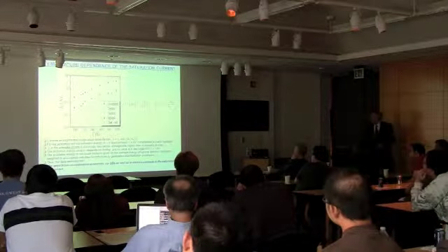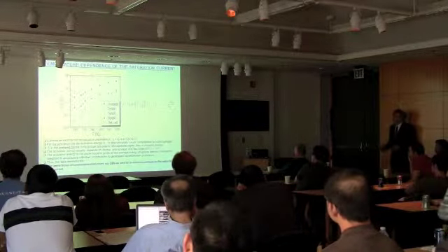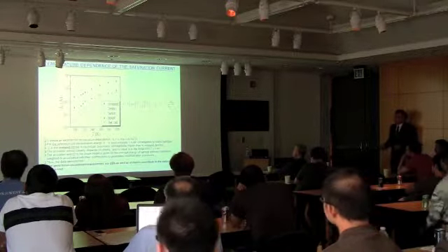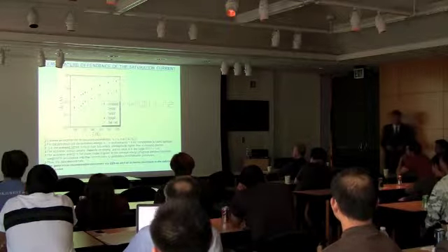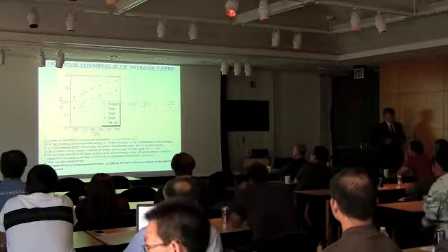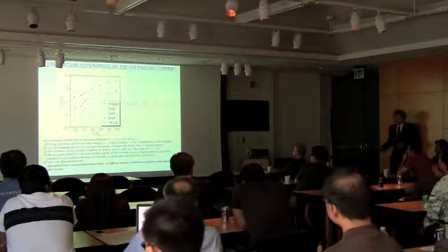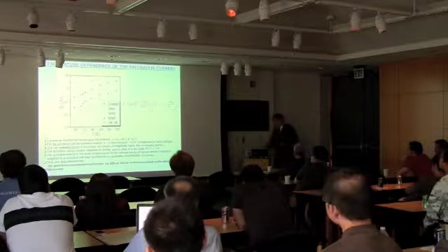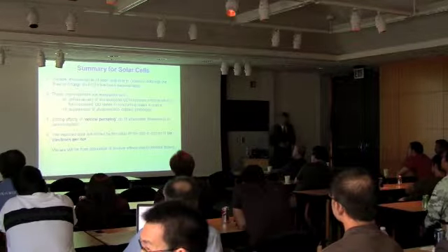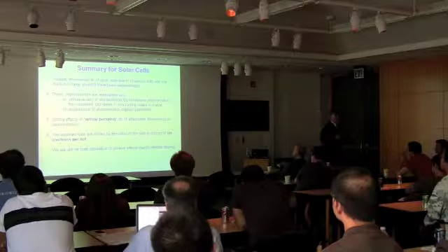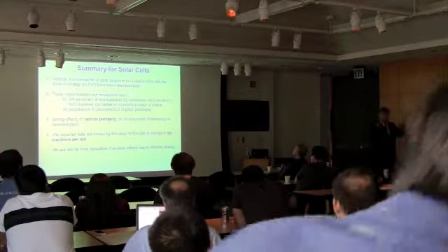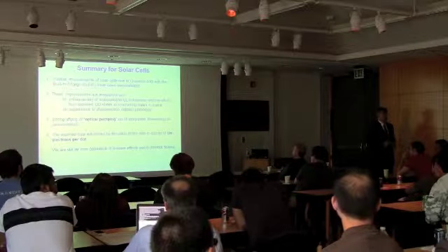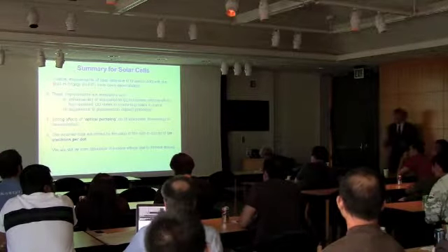You see, the reverse current, when we increase, first the current increased practically by 2 orders of magnitude when you put dots but don't dope those. If you start to dope, it drops down. So it means that there is a characteristic of the PN junction really demonstrating that yes, when you charge the dots in, then recombination in the material goes down. This recombination is due to the dots.